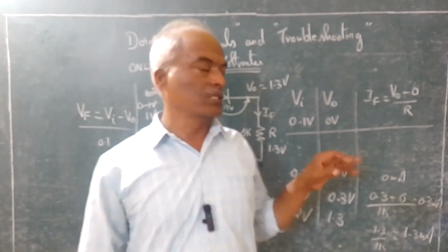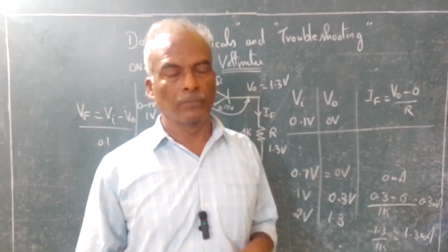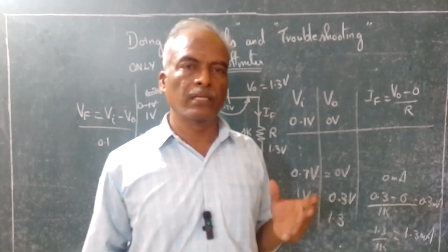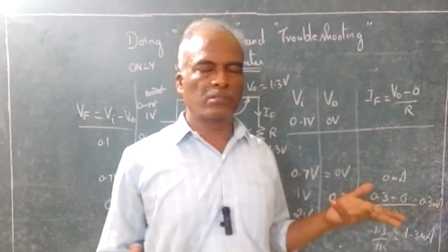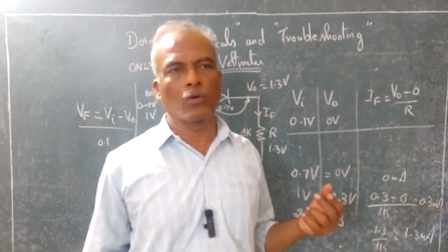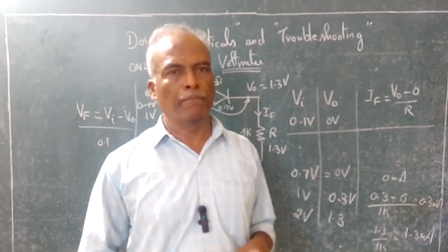Suppose I have written this just by looking at the color coded value. But when you measure with a Fluke, a standard very good digital multimeter, it may read out say 0.9K, 0.93K or 1.1K. It need not be accurately 1K.